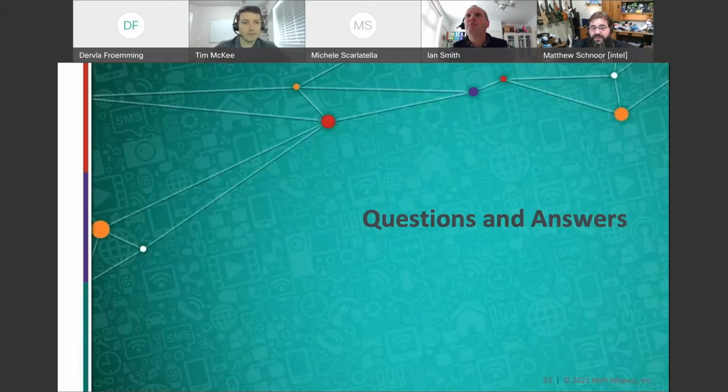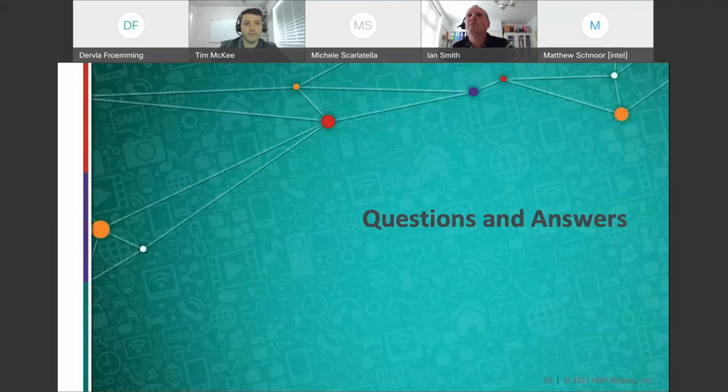And once it hears those things and listens for that and sees a recognizable stop, then it knows I'm on an I3C bus, and it knows it can actually initiate the hot join request at that point. Yeah, and you also noticed that the hot join slave address is very low, which has a high priority, so it will arbitrate very easily, and you can get on the bus very easily without the risk of collisions and delays.